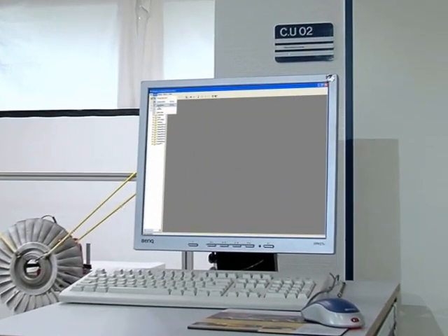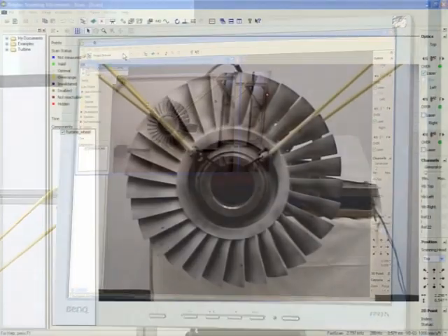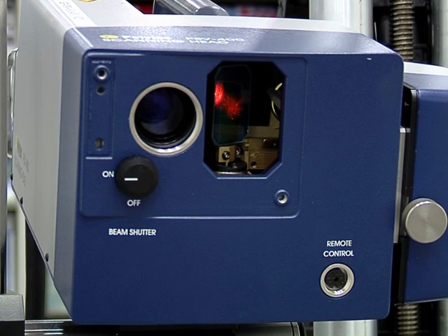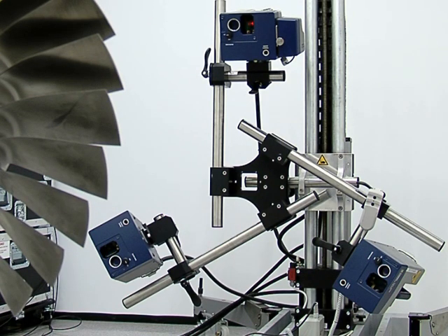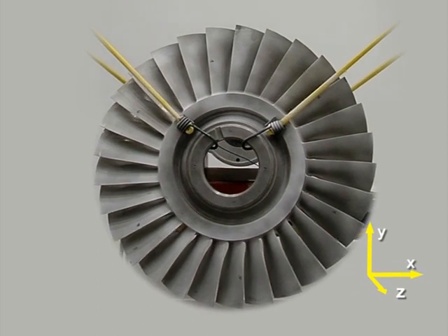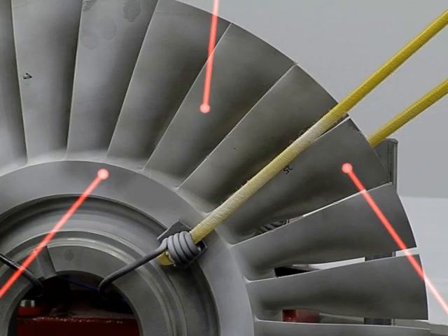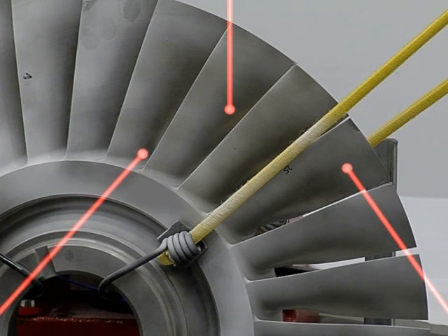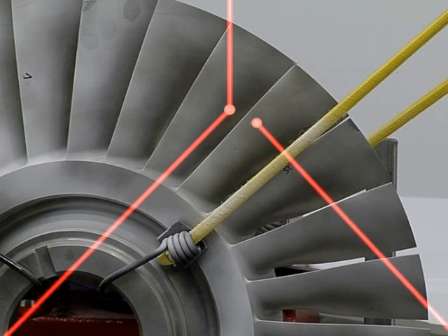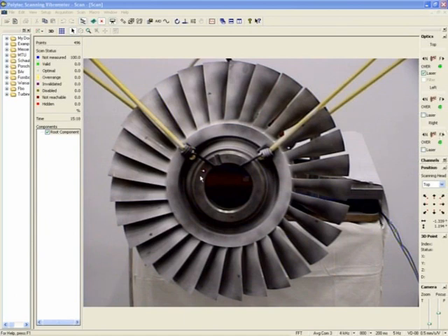Before the measurement can begin, a simple two-step process is used to determine and align the angle coordinates of the scanner mirrors with the camera image and the coordinates of the measurement heads with the absolute coordinates of the measurement object. In the first step, the software helps the user align the three laser beams to the object under test. Thus, the cursor position on the screen image of the structure corresponds accurately to the location of the laser spots on the actual test structure.